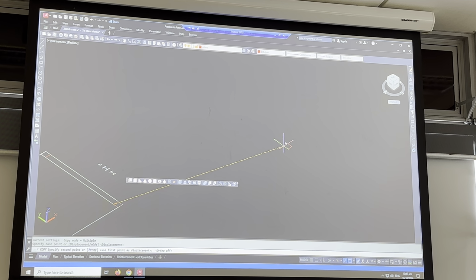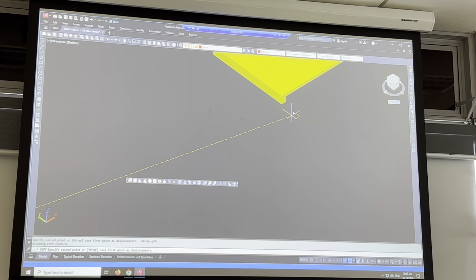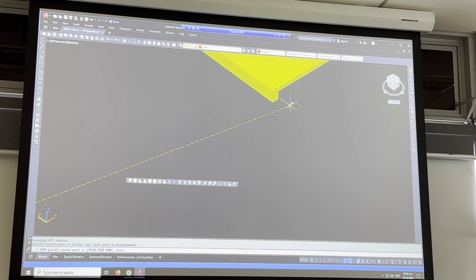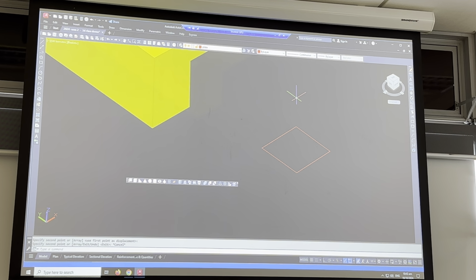Okay, so here's a little bit of a point of contentiousness. I've just drawn my plate at, I think, 400 by 400, but I said to you that you choose the size of your plate, and you'll have to do a wee bit of that plate design to make sure the bolts fit around the column.